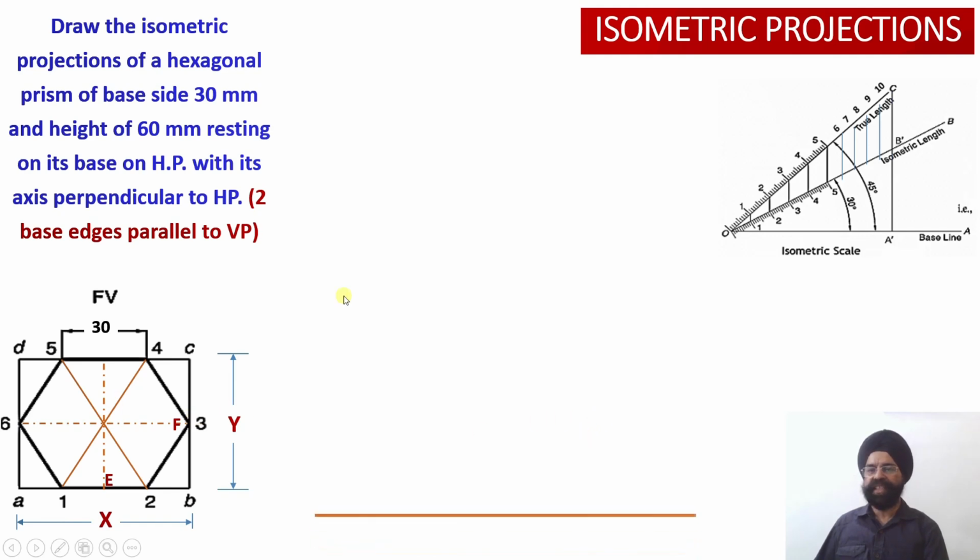Now all these distances we are going to convert into isometric length distances, and then the construction of the projections will be starting. So as usual, we have constructed the ground or the horizontal figure datum line. We are going to mark a point over here, and then towards the x-axis the 30-degree angle will be drawn, and the z-axis will be drawn again at an angle of 30 degrees with respect to this datum, and the height will be marked along the y-axis over there.